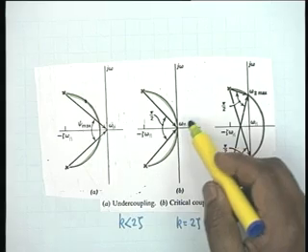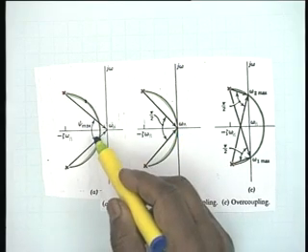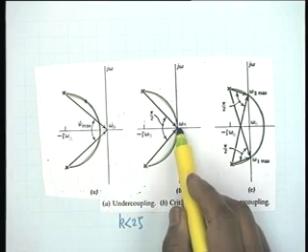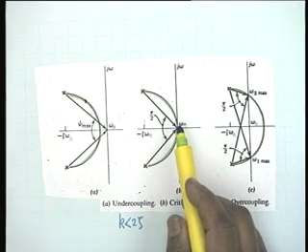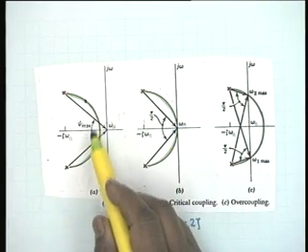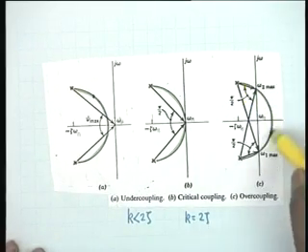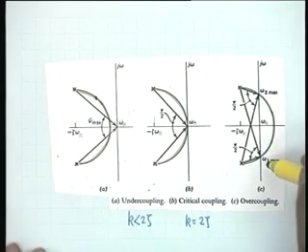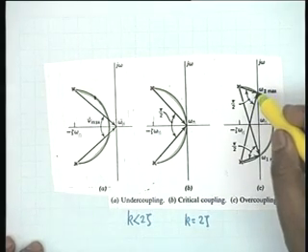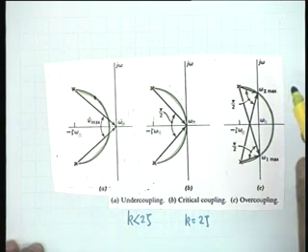coming here, the maximum occurs at omega n. Here also the maximum occurs at omega n, but this maximum is greater because sin psi reaches its highest value, that is unity. Here it cannot, because this angle cannot be pi by 2. On the other hand, if the peaking circle does intersect the j omega axis at 2 points, omega 2 max and omega 1 max, at each point the angle is pi by 2, and therefore there would be 2 maxima.